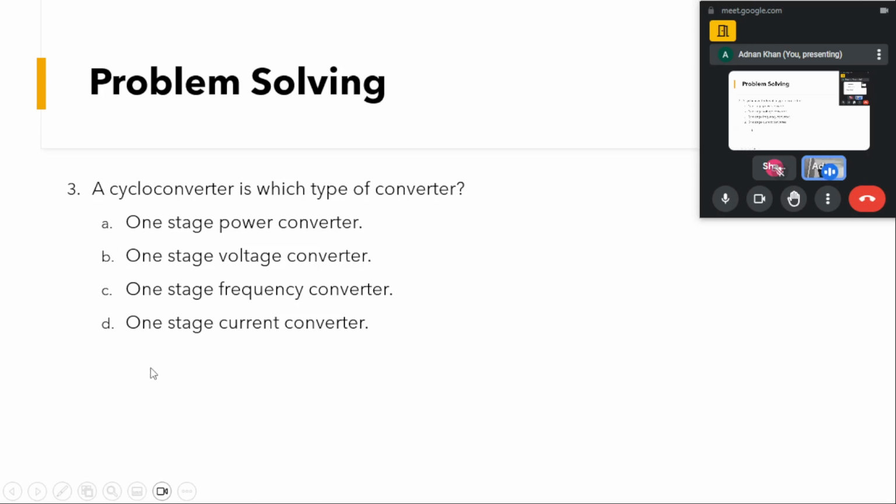Like first we do AC to DC, then we do DC to AC, and with our modulation, in the DC to AC conversion, we can have at the output ACs of different amplitudes and of different frequency as per our need by changing the modulation wave and modulations.